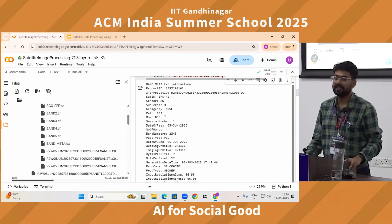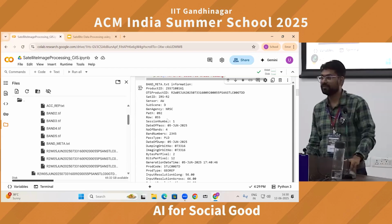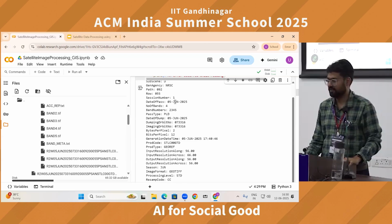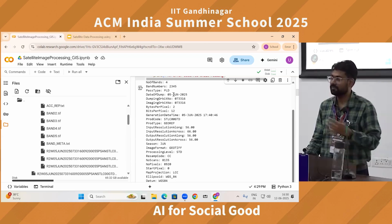Why is path and row important? Because the area on which you want to work will typically come on a particular path and row of the satellite. You have to know on which path and row it is coming if you want to order directly from NRSC based on the path and row information. The date of pass is 5th June, so the satellite took this image on 5th June 2025. The total number of bands is 4: band numbers 2, 3, 4, 5. Date of dump means the date on which this data was processed.